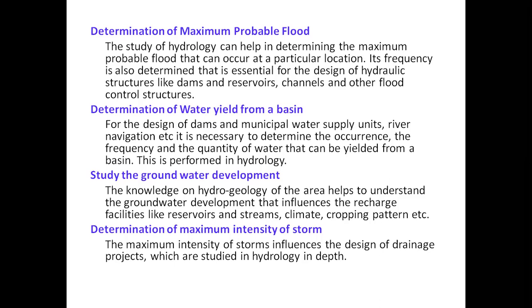In that area, we selected 222 hydrological wells, and every 15 days we calculated the SWL. SWL means static water level, and PWL means pumping water level. When water was running, after 1 hour or 2 hours, we collected the water from the borehole. That we call the discharge. All these things are part of groundwater development.